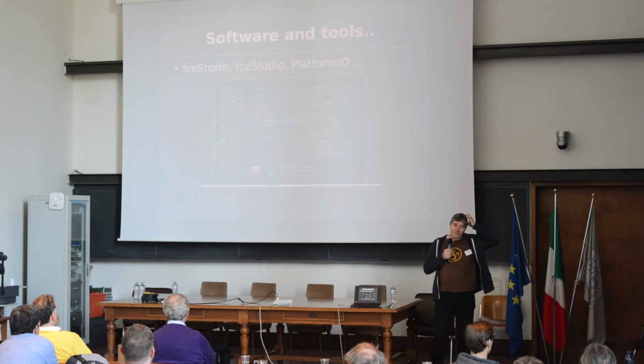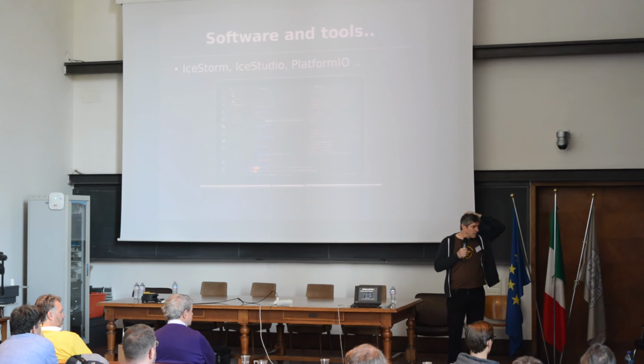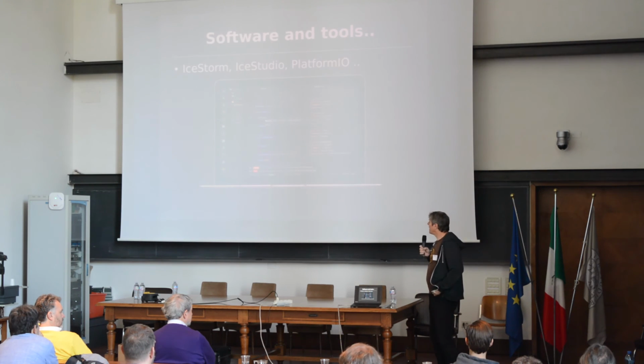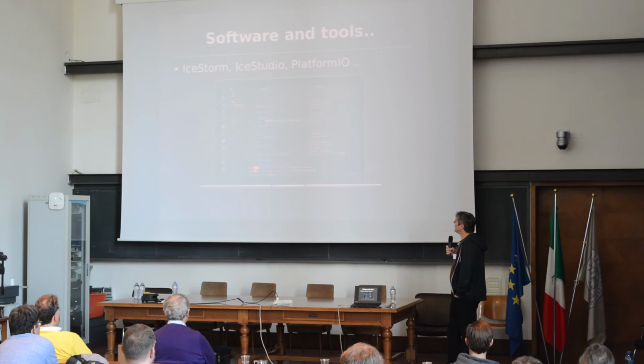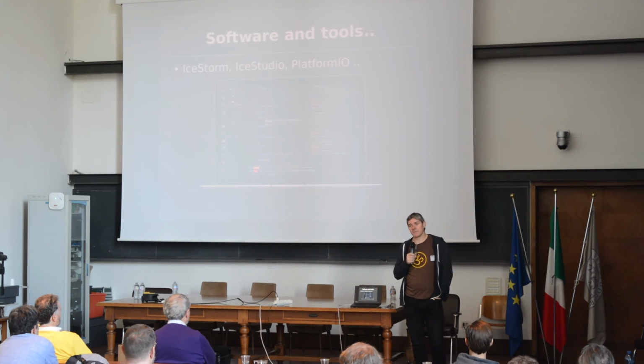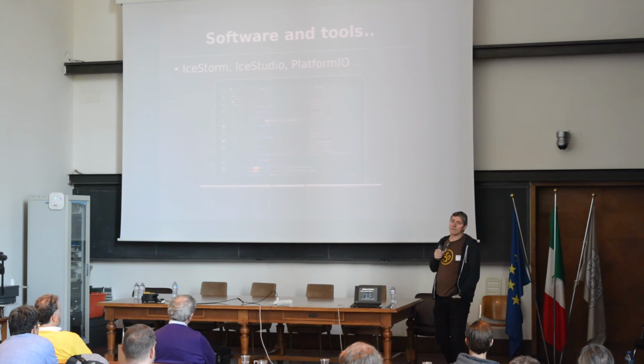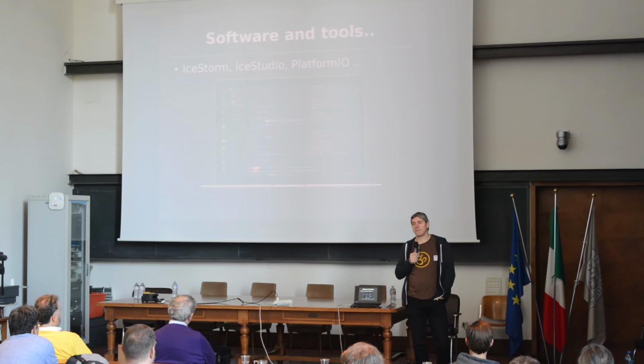Let me briefly talk about software and tools. One of the issues that we have, quickly on this, is obviously it's IceStorm based, and in order to get MyStorm working, you need an ARM compiler set, and you also need the FPGA tools, Yosys, and Arachne, etc. We found something called PlatformIO, which is now supporting both of these setups.